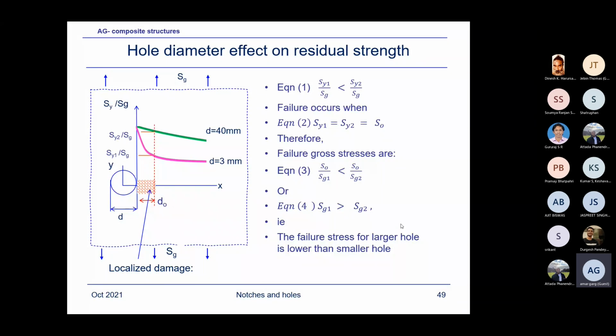We have to determine the unknown strength by testing a few coupons, and by testing a couple of hole diameters, determine the characteristic dimension, and consider the effect of the layups and diameters in order to properly account for the effect of these parameters on the characteristic dimension.